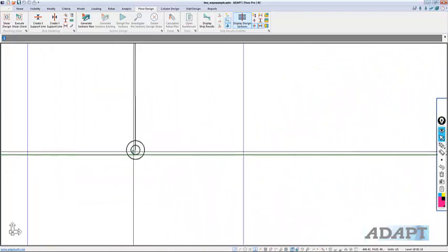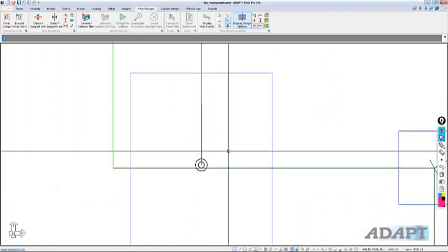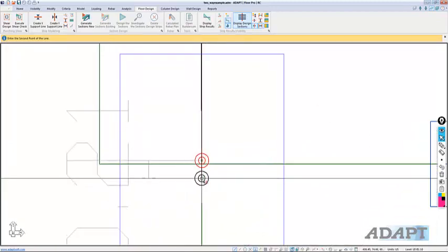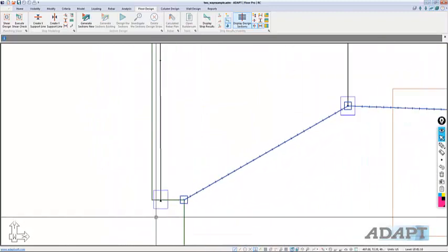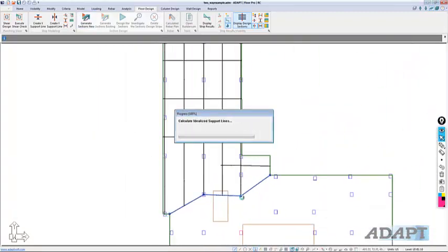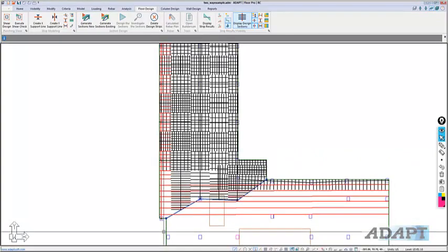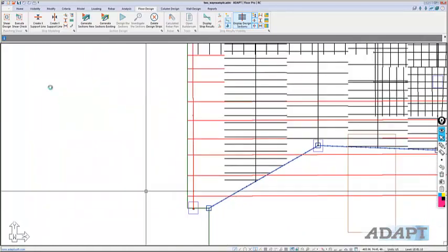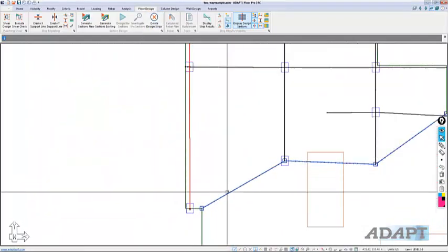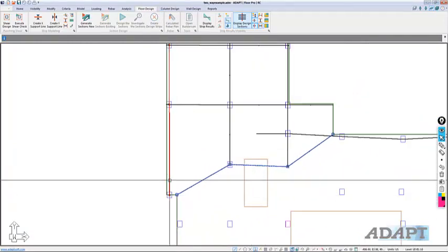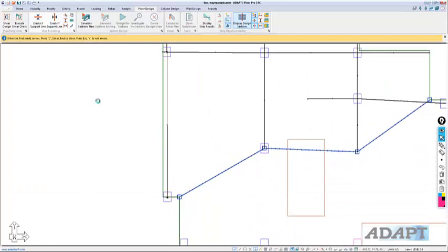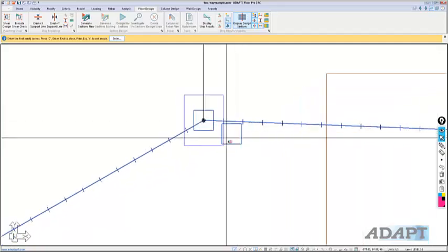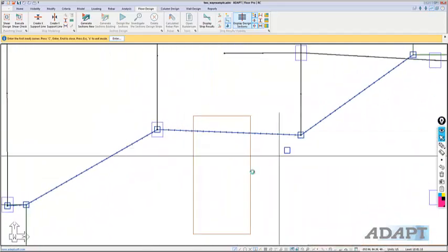And let's go ahead and look at this. So you see there's a little gap there, but there's no splitters, so that's causing the leak of that tributary. I'll close this off by just extending it outside of the slab. And then I could readjust it perpendicular if needed, but generate these again. The same issue occurs. We'll go back and fix that one more time. I'm just going to add another splitter like so. I want to make sure this is snapped properly.